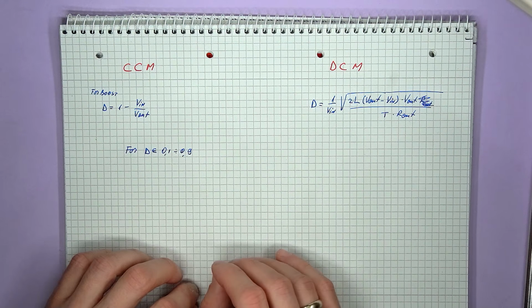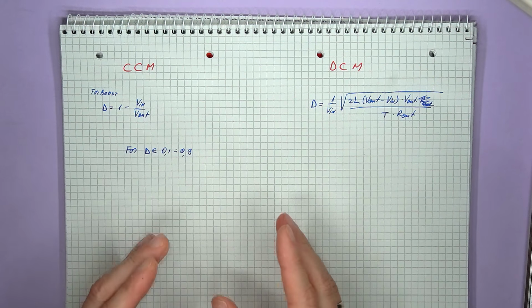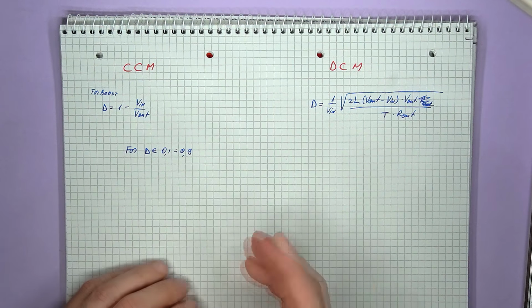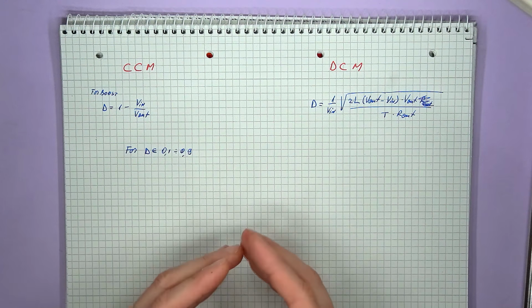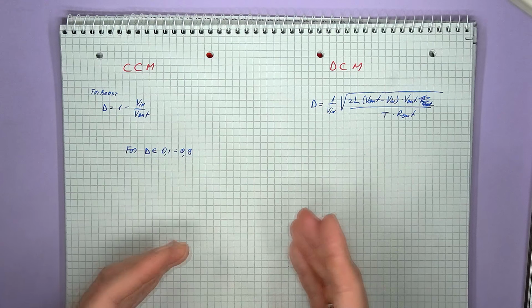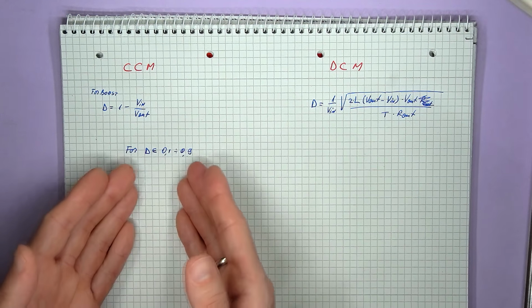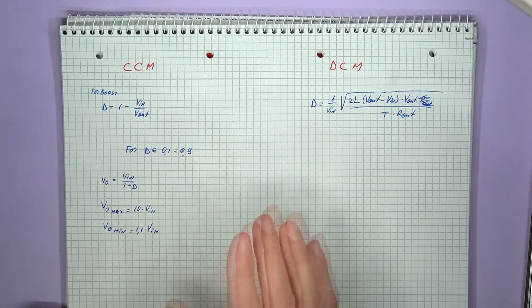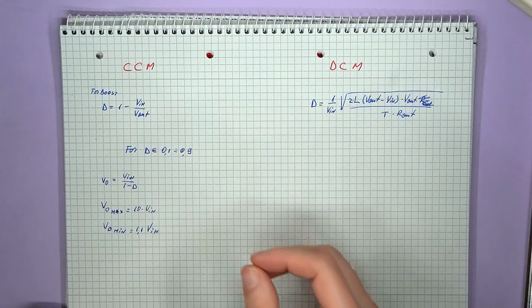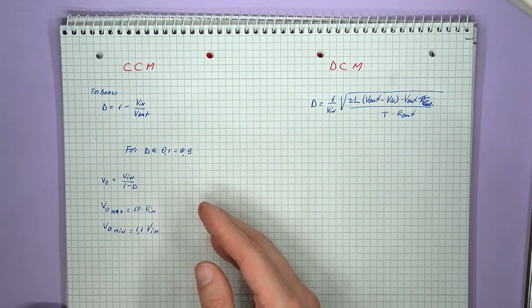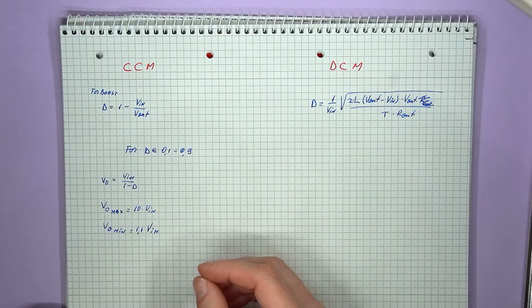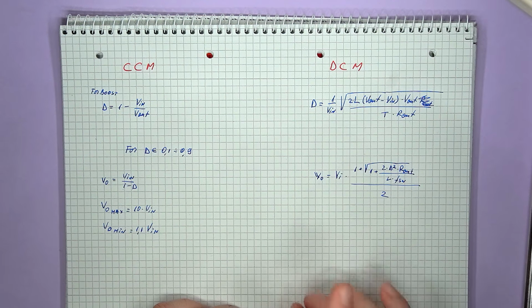Also, on the positive side, as long as the duty cycle range is fixed to some interval, in most real power supplies you can't get any value, there usually is a minimum and maximum limit. For the sake of example, let's say it's 10% and 90%. With this limitation in mind, under continuous conduction mode, the output voltage will be limited to a maximum of 10 times the input voltage. In discontinuous conduction mode, this limitation no longer exists.